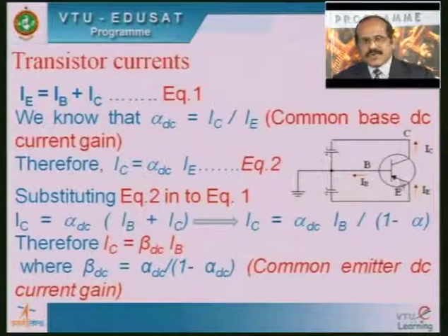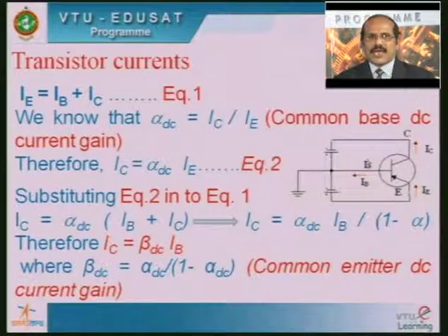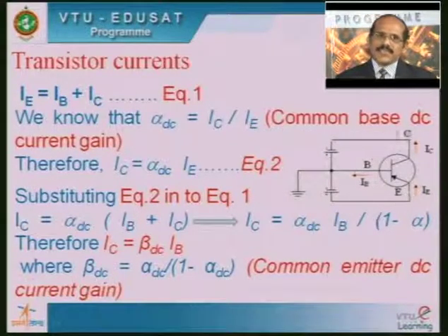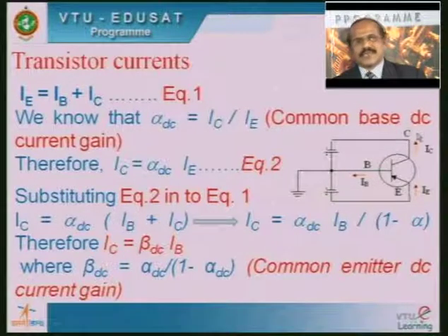So that's what you can note down from the emitter terminal here. The emitter terminal arrow is always towards the N type. Therefore the given transistor is PNP here. So this P acts as the emitter, this N acts as the base, and the other P layer, the extreme P layer, acts as the collector here.